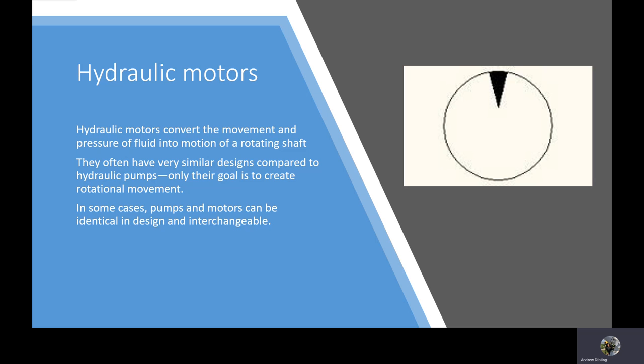As mentioned before, most of the hydraulic power is used in linear actuators. However, there is some use for hydraulic motors or rotary actuators, especially if you have a self-contained piece of equipment and you can power it by one power source as opposed to two, and where the motor needs to have excellent torque speed characteristics through a wide variety of speed regulations.